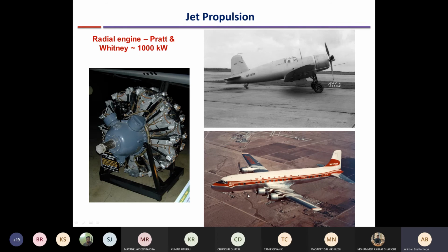You can see that this is a very old aircraft by looking at the windows. All the windows are square. Nowadays, we don't use square windows because of stress concentration. So the initial aircraft designers did not know that stress concentration can be a very critical factor.